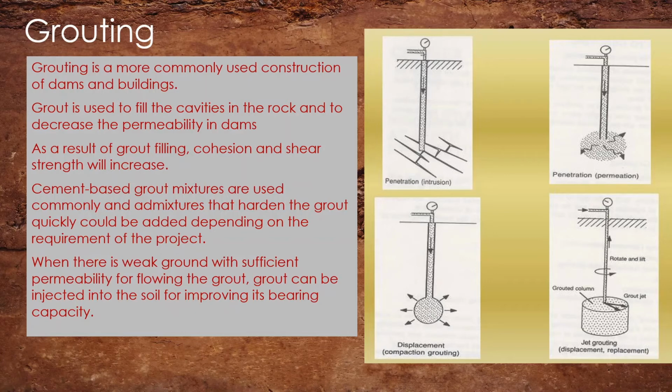Below the dam body. As a result of the grout filling, cohesion and the shear strength also increase. Cement-based grout mixtures are used commonly, and admixtures that harden the grout quickly could be added depending on the requirement of the project.